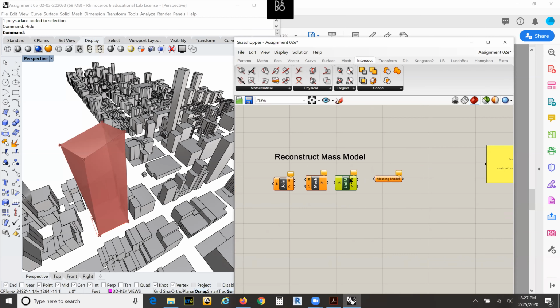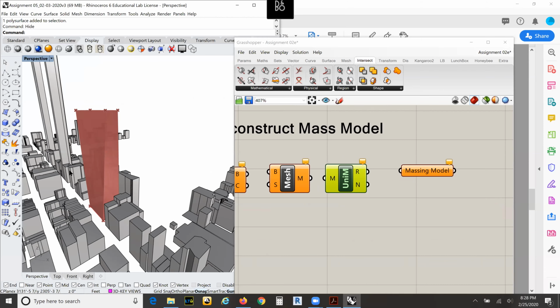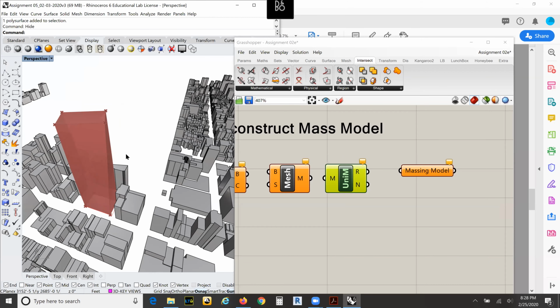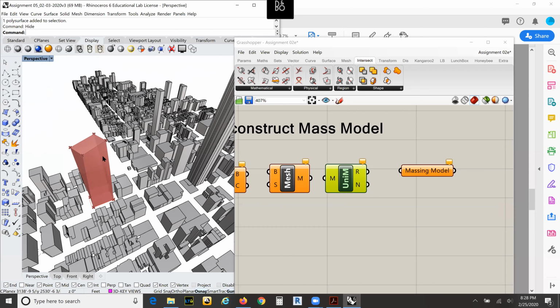So briefly, back in module 2, when we were talking about 3D modeling, and sometimes like with SketchUp, the mesh is flipped the other way. It's supposed to be white, but then it's flipped and it's actually a gray base. Well, sometimes that can happen in Rhino for meshes. And like I said, the computer is stupid. Sometimes, even though all these meshes are created the same way, the computer gets confused and it flips a mesh. And when the mesh flips, the simulation won't read that mesh correctly.